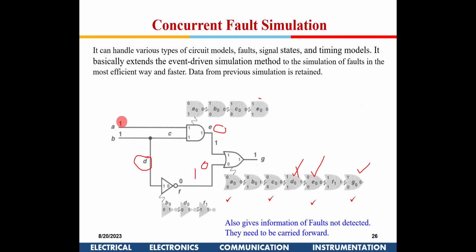So if you see here, in a single run, single run means a single test vector, it will do simulations many times by replacing these gates with what are known as the faulty gate models, corresponding to this gate, for each fault it has got. So it will have more faulty models also, right? But for this particular test vector, these are the corresponding faulty gates. So it will put one gate at a time and do the simulation. Okay, one fault at a time.